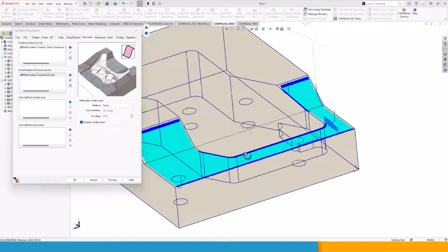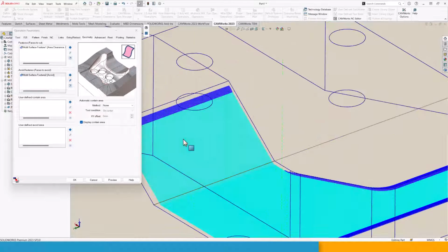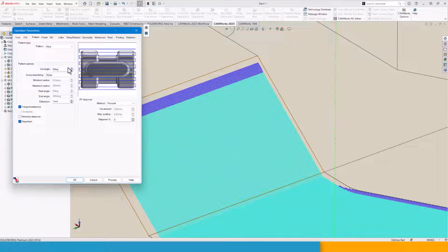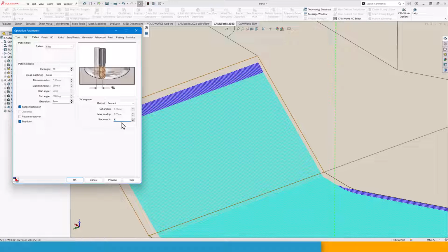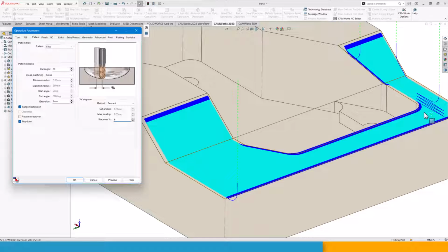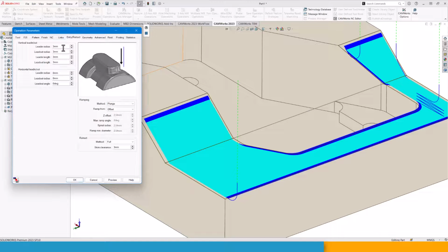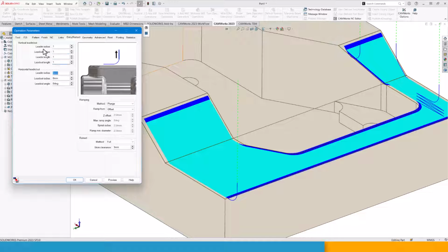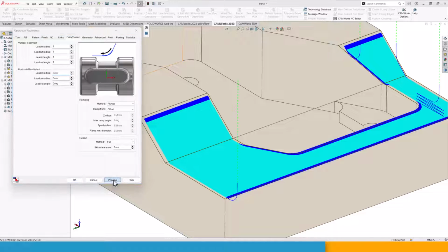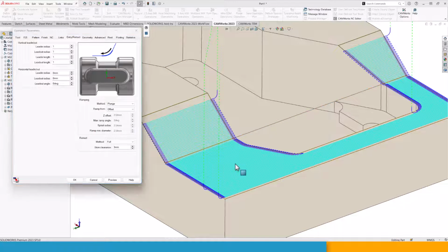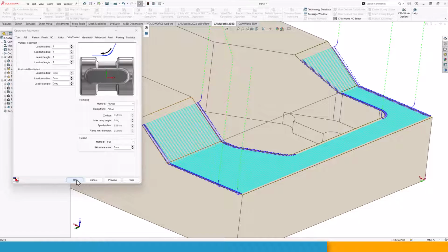So we can see that we are not doing too bad. Now we are running in the wrong direction, I would say. So let's just rotate this by 90 and let's just crank this up, let's say 6% instead. And I can also see that we have like ramp lead-ins, so we can do a plunge. If you want to, you can even change these to smaller values. Everything is up for editing the properties, so everything should be perfectly fine at this point.